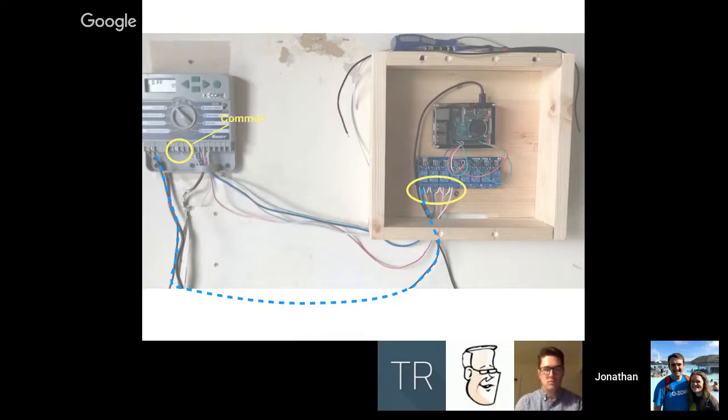But on my controller, where the common line comes in from the sprinklers, it looks like a normal sprinkler wire. It's just with the same stuff. My controller just couples that together and has two separate contact points for it, for whatever reason. So yours may be the same, or you may need to figure out which one's your common wire and connect it just to the other end of the 24-volt AC.